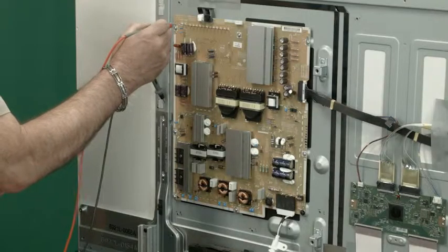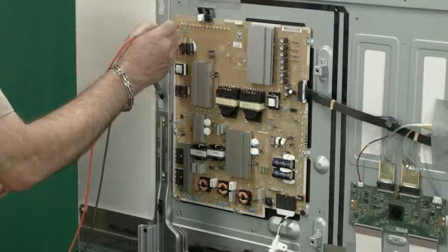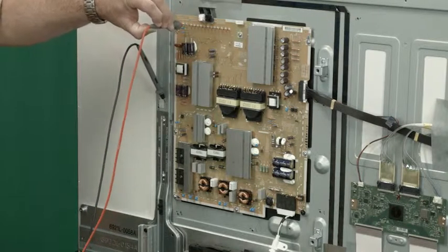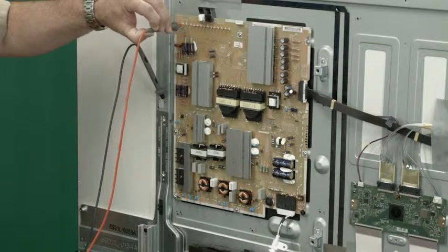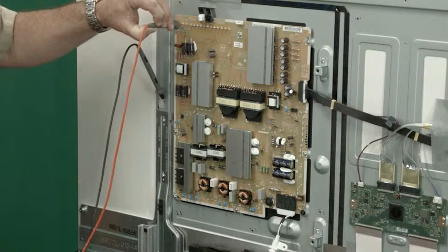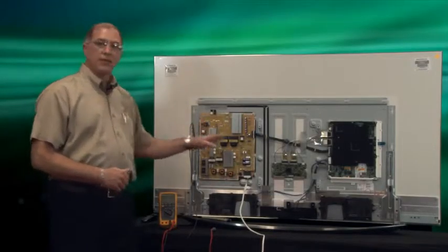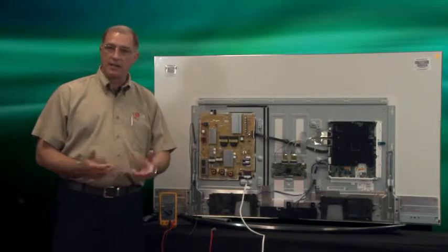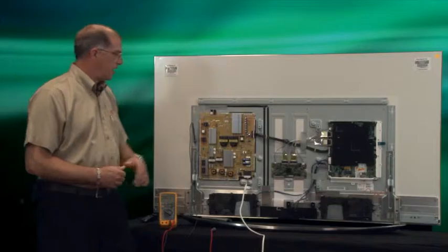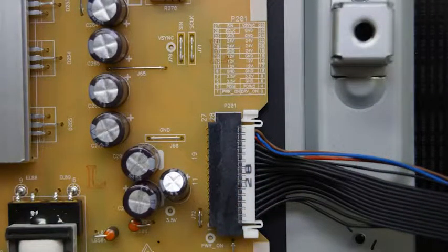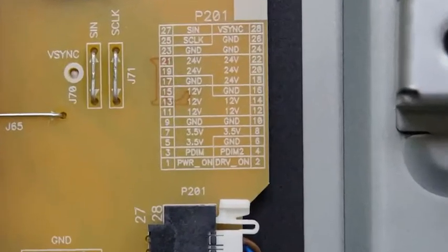But the output voltage of the inverter will change dramatically. In some of the new 2015 models, the output voltage can actually climb to its normal height or normal voltage level, then go to roughly 200 volts or above. When you're checking the voltage for PDIM to make sure it's present when your LED indicates that you're missing PDIM information, make sure you refer correctly to the chart that's on the power supply as to what pin PDIM is.